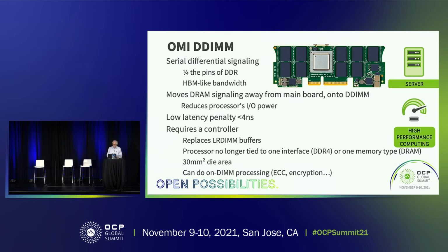Since a controller replaces the buffers on the LRDIMM, it adds much less than 4 nanoseconds to the DIMM's latency, so it's a very small latency penalty. The controller itself is not a large chip, so it's not expected to add all that much to the cost of the differential DIMM. Future versions will not only be able to support enhanced functionality, but will also allow a processor to communicate through OMI with a variety of memory types.